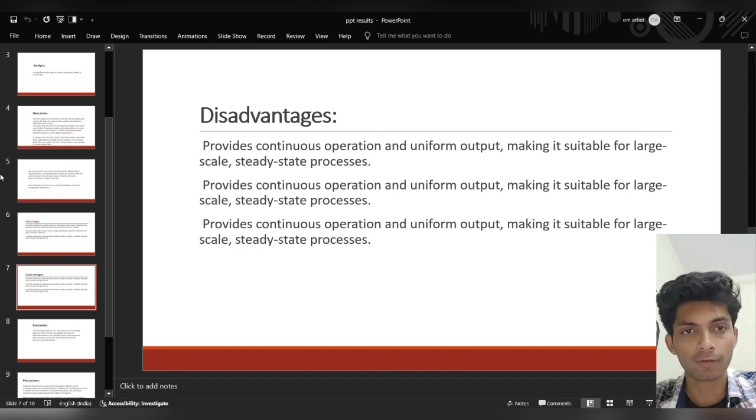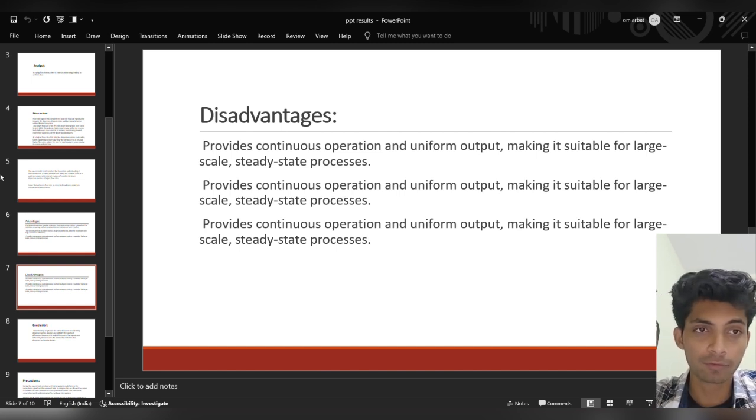Now secondly, for a higher flow rate of 20 lph, potential maldistribution: in cases of uneven flow, channeling or dead zones may occur, reducing reactor efficiency. Plug flow systems are less adaptable to feed concentration fluctuations compared to fully mixed systems. Heat and mass transfer limitations: limited mixing can restrict heat and mass transfer, affecting reaction rates.